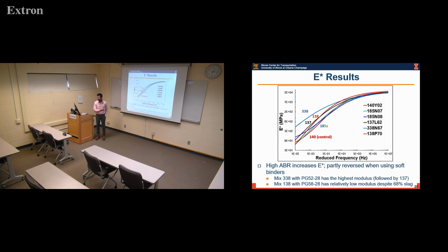But he's talking about just plotting a bar chart showing, let's say, 20 degrees Celsius, 1 hertz or 10 hertz. Yeah, because it has a direct relation with fatigue, so it can be a good indicator if fatigue is not performed. Yeah, usually, not in this project in particular, but in all of the projects, we think, okay, I'm drawing the master curve, I see that it's higher or shifting. But usually we're not seeing that, we're seeing that they are overlapping. So maybe we should find a better way of representing this data, because this is a very important thing.